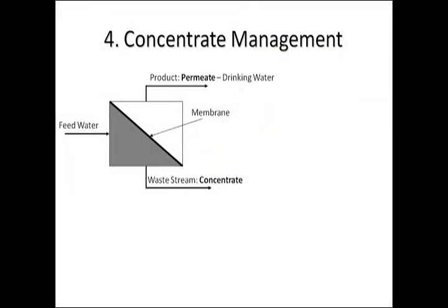The big one to me is concentrate management. Ed mentioned this as well. He pointed out they're pumping their concentrate 22 miles or something like that to put it into groundwater re-injection. What happens is that we have to worry about that. And I've used this slide because I want to emphasize that the product, if it's drinking water, is some percentage of the feed water, and the concentrate is the rest of the percentage. And so if there's anything we can do to reduce the amount of concentrate, we're going to increase the amount of product water or drinking water we have there.